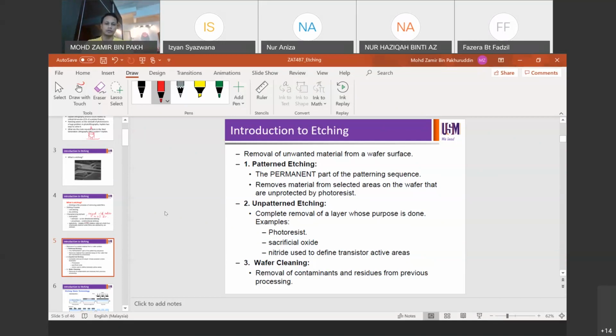Well, this one you can also consider photoresist, the resist, as blanket. That means if the resist has no patterns yet, you can also remove the whole resist completely. It can be done as well. But on the other hand, you can also remove resist in the pattern etch where the resist already formed the pattern. So it can be both, depending on how to use the etching.